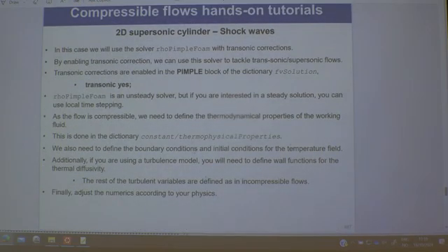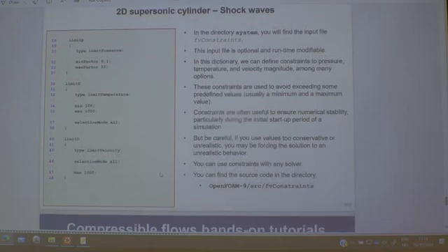So for this setup here, they have set up some hints how this can actually be done. And I must admit, I tried to simulate that one, and I couldn't make it work. It crashed all the time. So it's not necessarily so easy to set up such a problem, or it's just me that is stupid. It crashed because I got negative temperatures, and that's not so good. The temperature should be absolute here in Kelvin, so when that one goes negative, then not good.